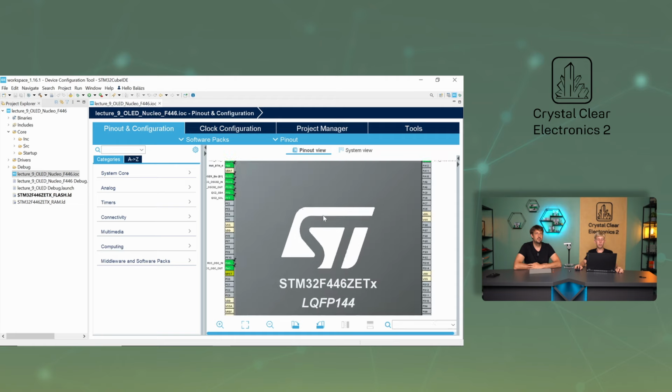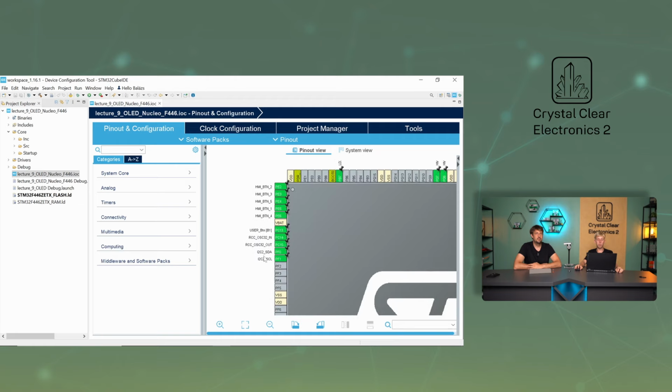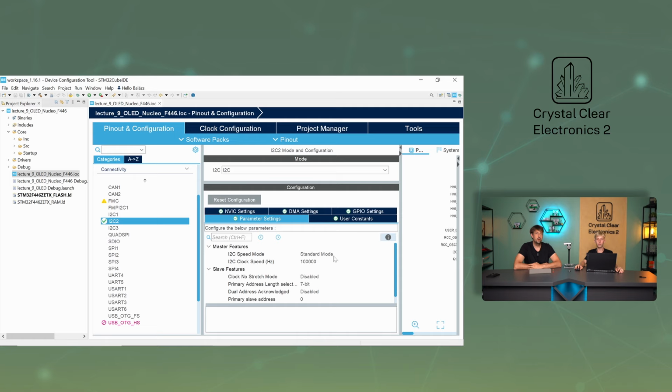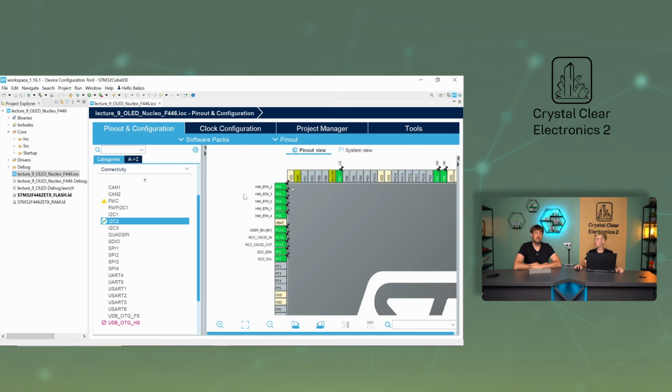The I2C SDA and SCL legs are connected to the pins PF0 and PF1 according to the hardware associated with the I2C peripheral 2. The communication protocol setting can also be seen by opening the I2C menu item, which is as follows. Other HMIs are also part of the project, some of which you may already be familiar with. For example, we have inserted our 3 push buttons called HMI button 1, HMI button 2, and HMI button 3. For now, do not change the code, let's stick to the original configuration.